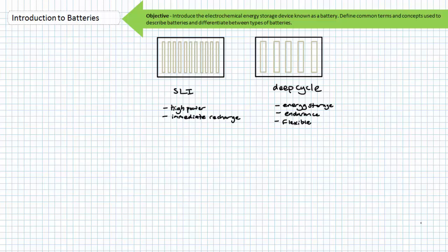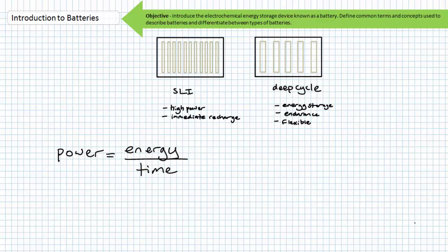Additionally, deep cycle batteries used to supply an off-grid application may experience irregular charging and must be flexible in nature. Intermittent renewable resources might charge a battery slowly, yet a backup generator will charge a battery quickly. Additionally, consider UPS applications in which a battery is on constant standby and only expected to back up a load for a brief grid disturbance or initiate an orderly shutdown of the affected system. This is to suggest that no one battery design does it all. At the two extremes are starter and deep cycle batteries. A starter is a sprinter and designed to deliver a large surge of power for a short duration.